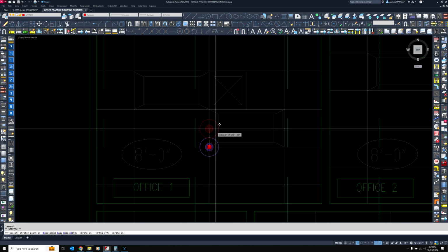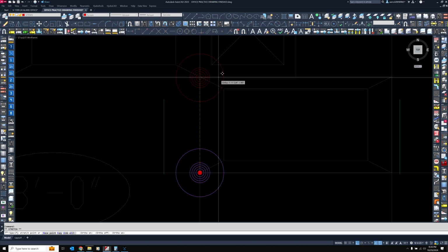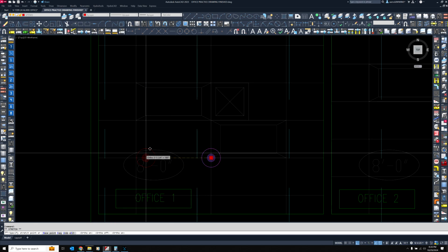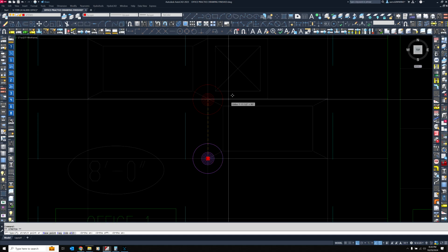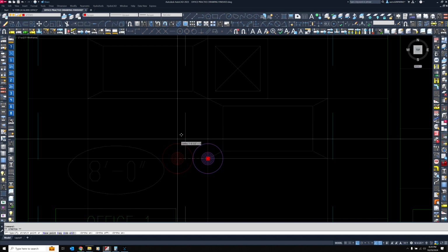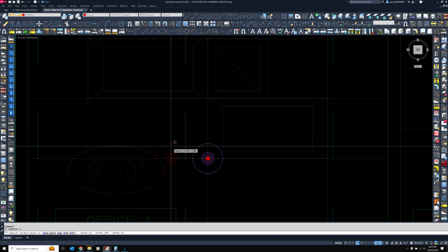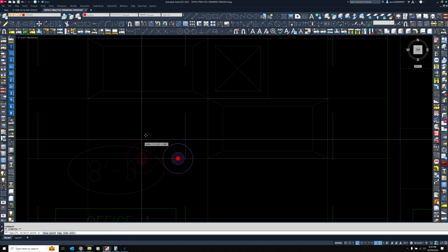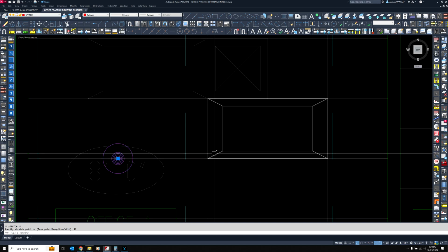I want to go up 12 inches because we talked about this in the beginning, I believe. These are 2 foot by 4 foot ceiling tiles. And most projects, they're going to require us to go at what they call the quarter point or the center. And the quarter is 12 inches in, 24 inches in, or maybe you're 12 inches off the other side of the tile. So think of it like rows and columns.